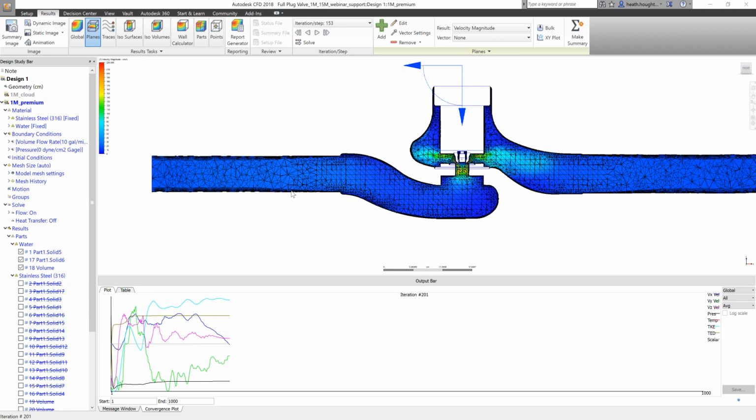And that's expectations. If you start running simulations where you're like, well, I really didn't get much performance gain out of that, we want to hear about it, because the technology exists in the background. It's, are we utilizing the resource effectively for that problem? Do we need to tune what we call solution control, and how fast and how little we relax the solution to make sure it's stable? We might need to fine tune things a little bit here and there, and that's what happens with experience.